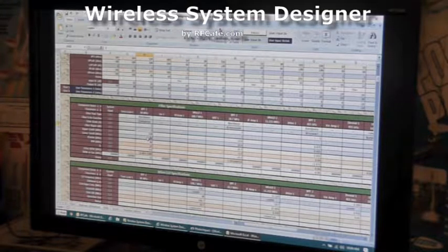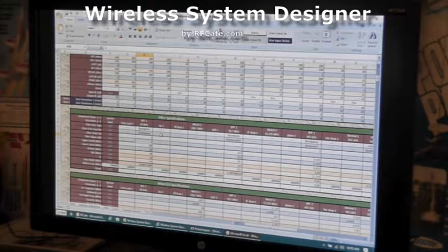And then upper and lower cutoff frequencies, the band pass and band stop need both. The low pass requires an upper cutoff. The high pass needs a lower cutoff. So it'll warn you if something's missing there. And it calculates, based on your inputs, what the center frequency and bandwidth are, and it calculates what the Q of the filter is, the Q being the ratio of the center frequency to the bandwidth. Again, all standard calculations.